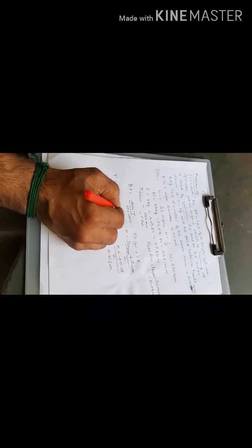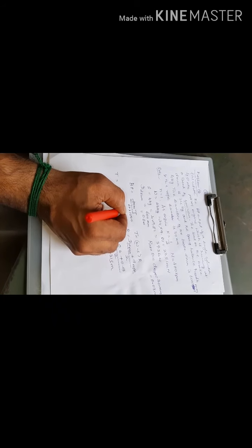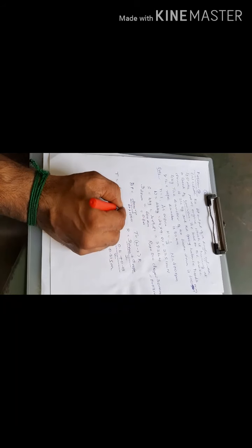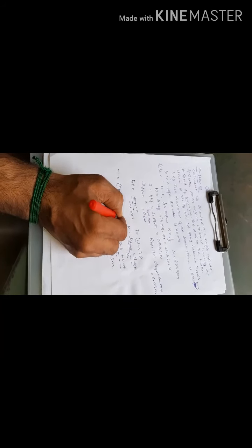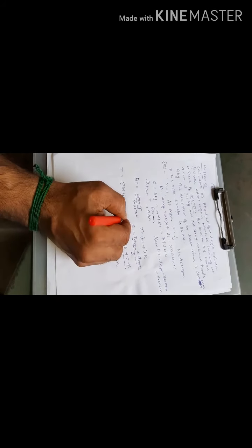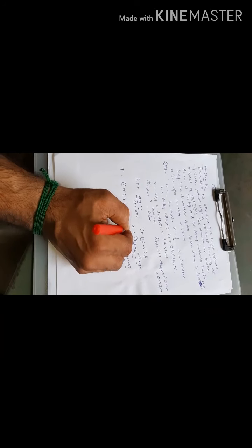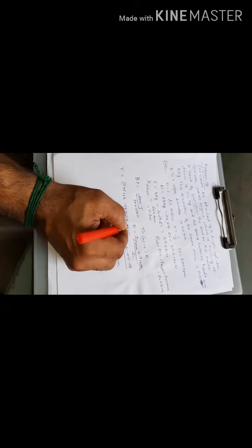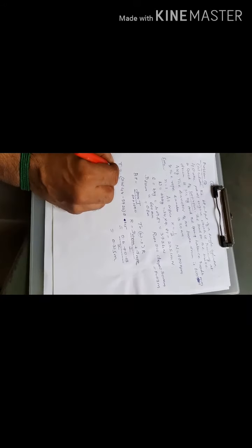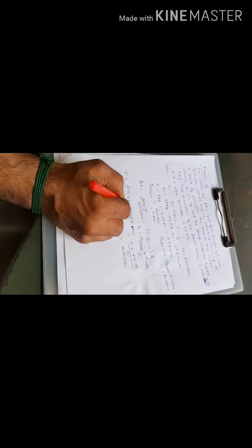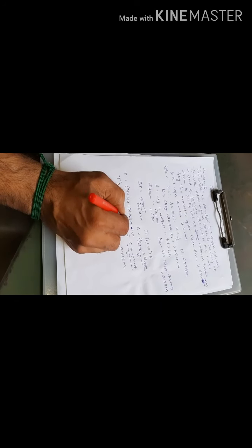So therefore, torque is equal to W, which is 235.44, minus S, the spring value of 4 kg, that is 39.24 Newton, multiplied by the R value, which is 0.315. So torque is equal to 61.8 Newton meter.